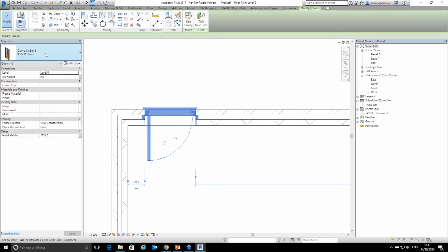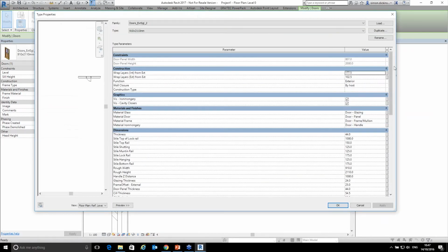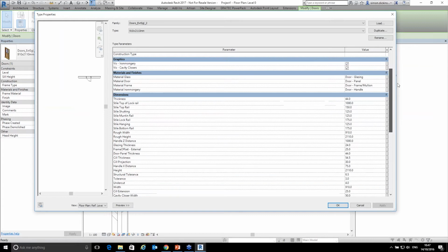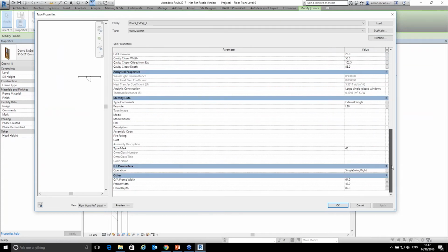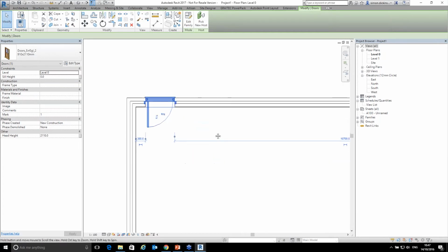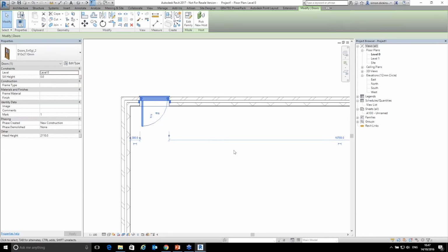So this wall construction, based on the materials that I'm using, has a U value of 0.2. So straight away we've got the benefit of not only just designing, but the ability to maybe export this information out to our building analysis packages or building analysis people, and actually get the next level of information added into it. So some very powerful features straight out of the box for creating that.